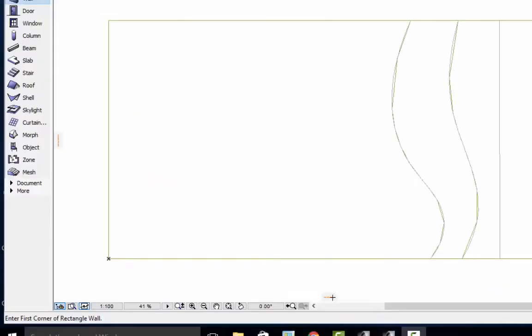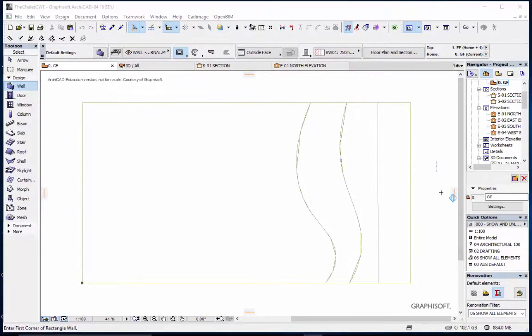I just want to talk about these little tabs you can see on each side of the work area here. They're reference lines, and I can drag one and bring it to the edge of the block like that. I can also drag one from this side and snap it to the edge of the block. And this helps me with measuring and setting up. So now that I've got those two reference lines there, I'm going to get a position for the start of my wall. If we look back on the plan again, it's 9 meters in and 10 meters in from the front.